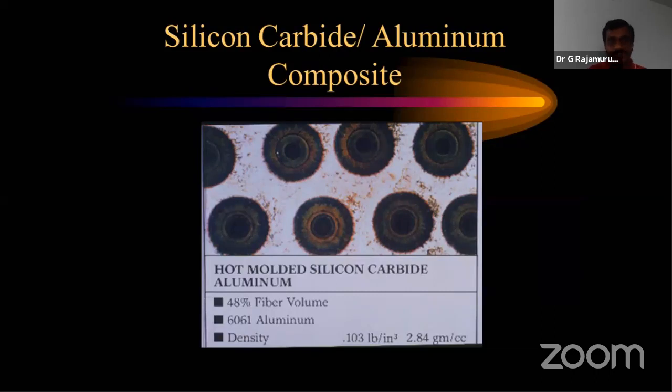Okay, so for that also you are doing the stirring action. So when you do the stir casting technique, what is the purpose of using the stirrer? While stirring that molten metal, you are able to distribute the particles evenly over the entire volume of the metal. That's why we use the stirring. And even in the stirring, you should not use a maximum speed of stirring. So an optimum stirrer speed should be selected. Otherwise, all the particles will be clustered on one side. Then you can't expect even properties on the entire matrix.